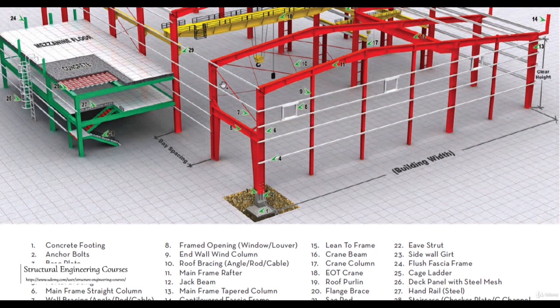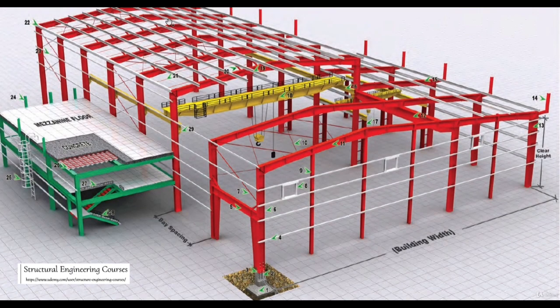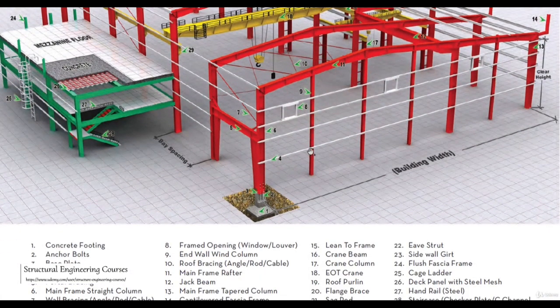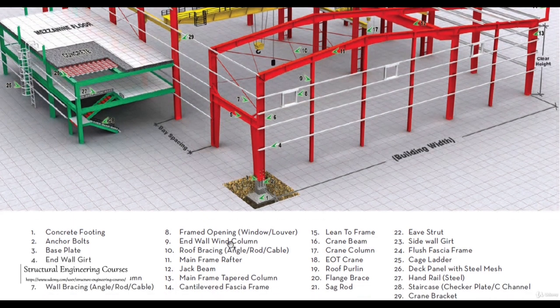So basically, these are the portal frames, and this is also called a gable end frame. At the end frame, we make sure that if we want to make a sheeting, we do need these wind columns also. The purpose of these wind columns is to make sure that we can make these wall girts also, and to effectively make a perimeter around the whole structure. So this wall wind column is a must, an essential for a PEB structure.